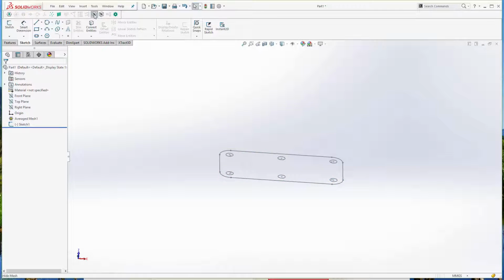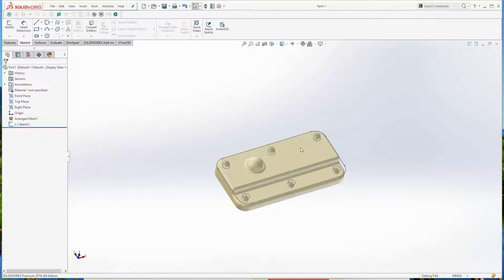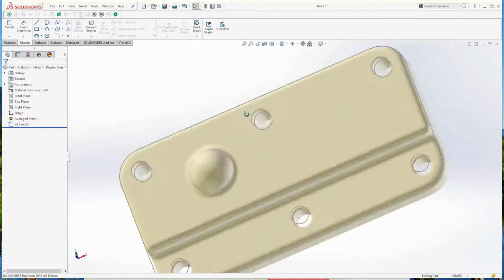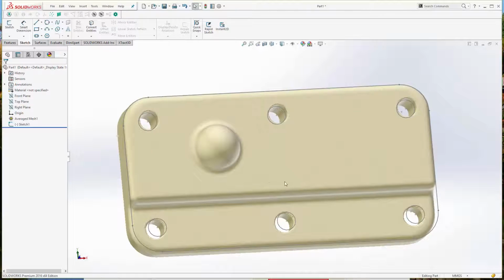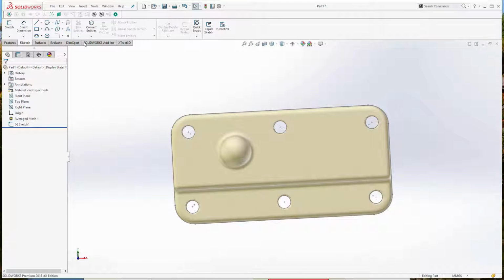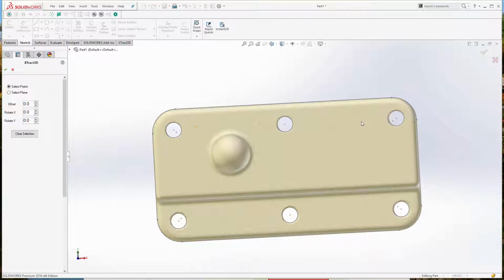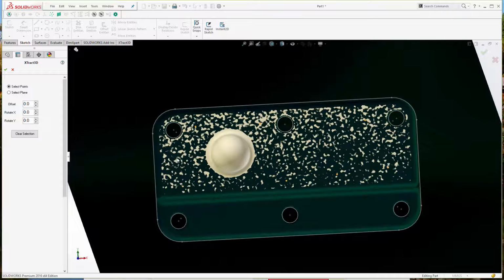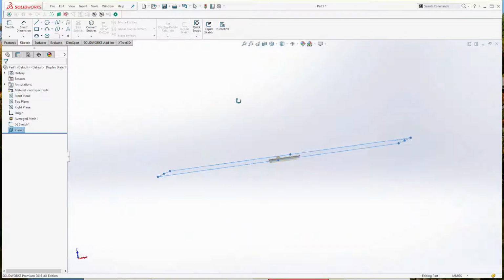So let's have a look at our mesh again. So next thing I want to do is probably just extrude it up and down to the plane. I can just pick a point, or I can create planes. Normally I just like to do a point because it's quick and easy, but in this case I want it to be a little bit more accurate, so I'm going to create two planes. We have a plane tool here, and I can do it by just sampling a handful of points that I'm really interested in. So that'll be one plane.